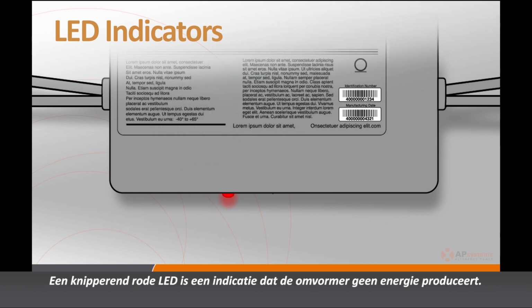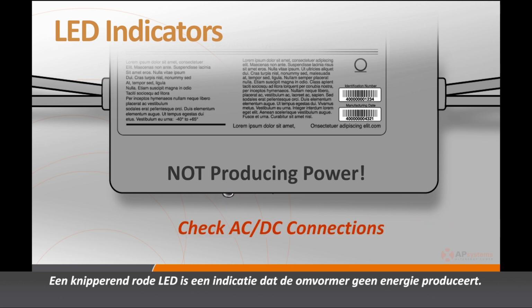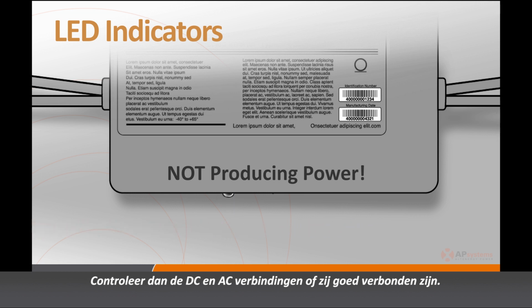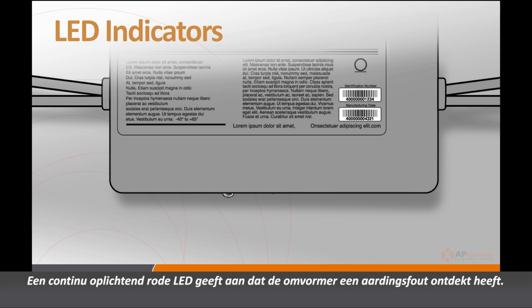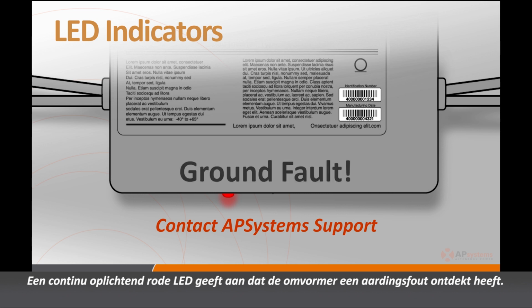A flashing red LED is an indication that the inverter is not producing power. Check the DC and AC leads to be sure they are securely connected. A solid red LED indicates the inverter has detected a ground fault.